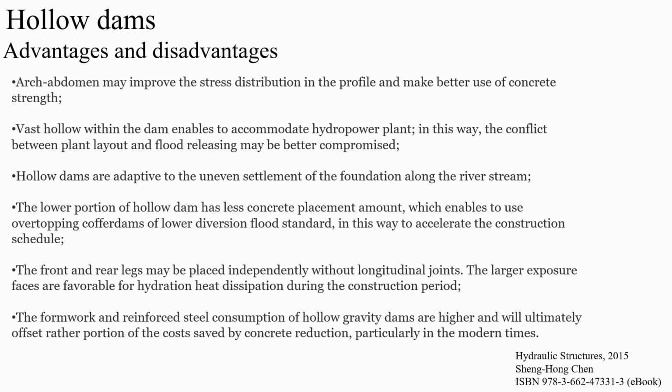The front and rear legs can be constructed independently, which helps in large exposure area for dissipating hydration heat during construction. However, the formwork and steel reinforcement are higher and will offset a large portion of the cost saved by concrete reduction.